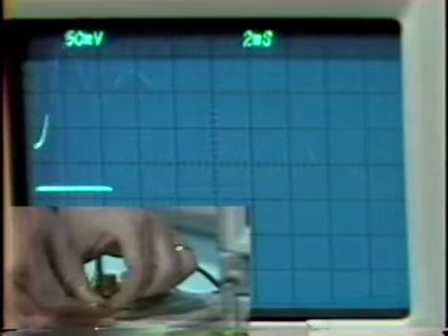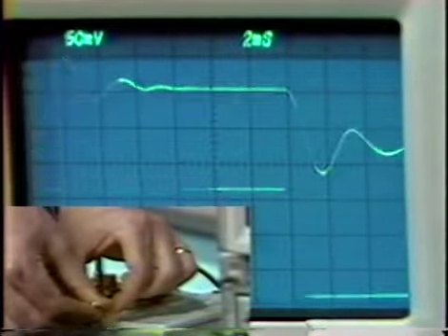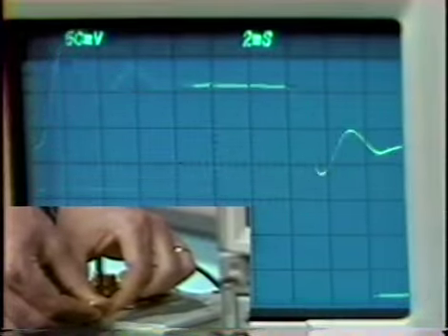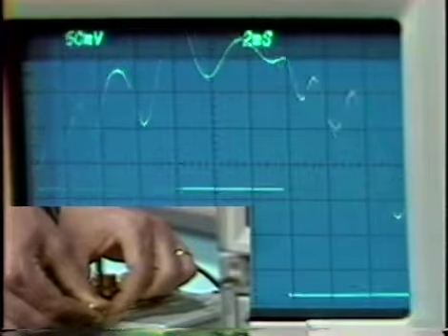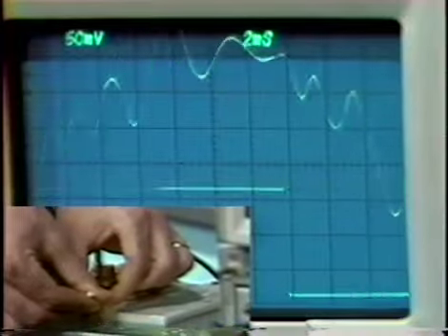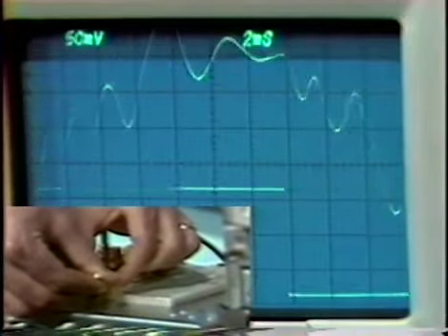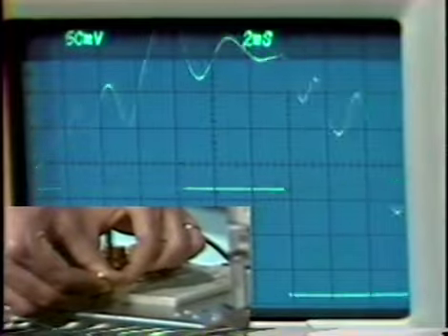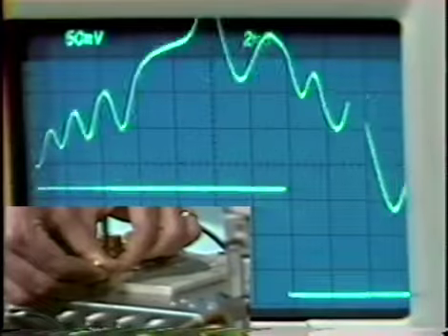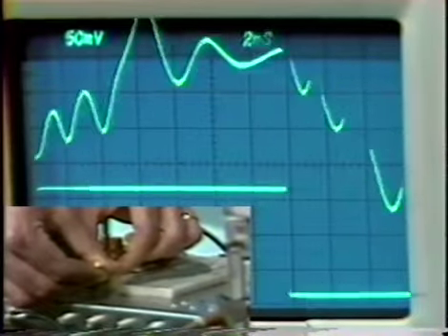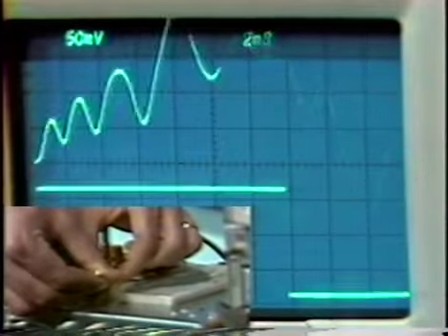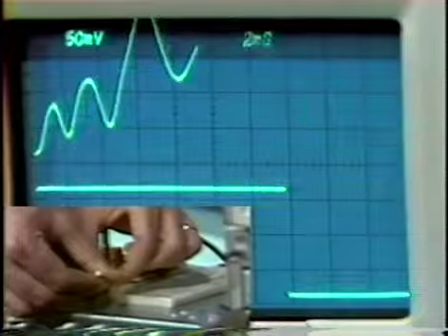And if I do that with this potentiometer, which simply adjusts the amplitude of the signal applied to our external generator, well, we notice we can get quite bizarre modes of behavior in the phase-locked loop, really very poor performance. And what's really happening here is we're commanding such a large frequency excursion at the input that the loop can't really keep up. We skip a couple of cycles. The phase detector is cyclical, as I mentioned. We jump a few cycles. The recovery from that is quite tortured.